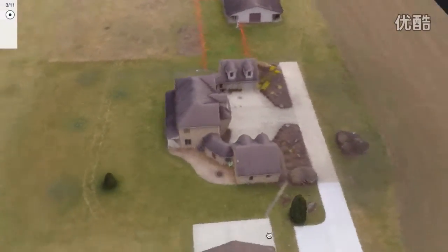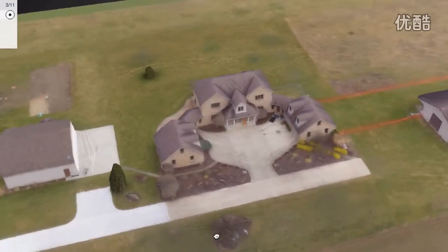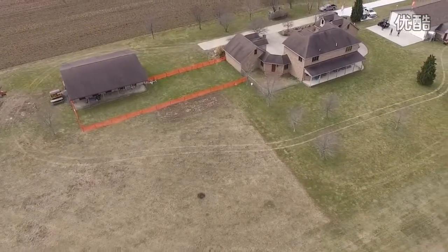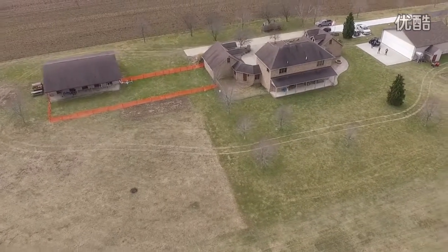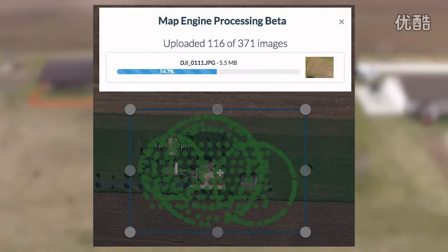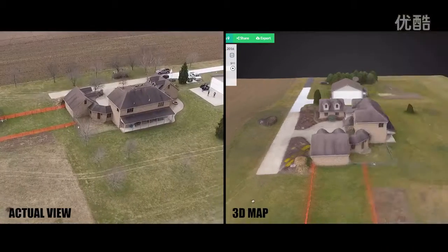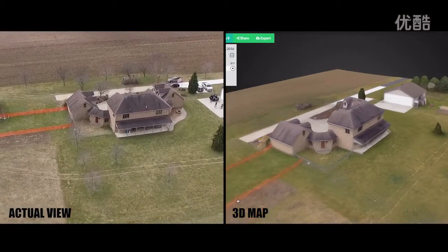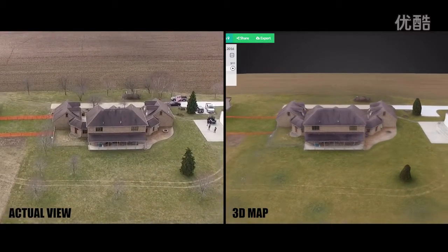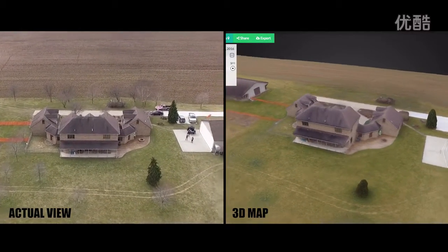Okay. And through that, there are some automated flight modes that DJI has, and one of them is point of interest. With point of interest mode, we were able to orbit at a 45-degree angle around the same altitude that we flew the original mission, and then we were able to get a side view of all those buildings. The 3 buildings that we were trying, we orbited all 3 of those, and the results were drastically different.